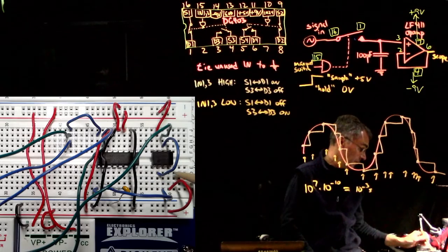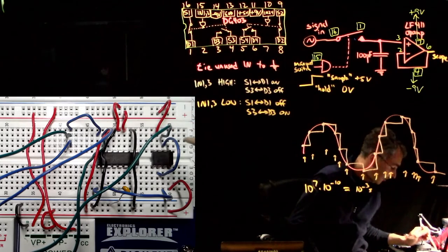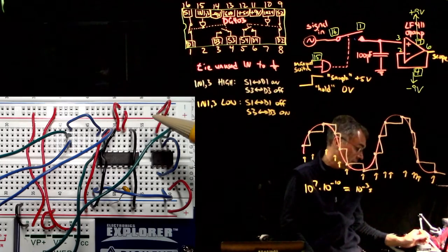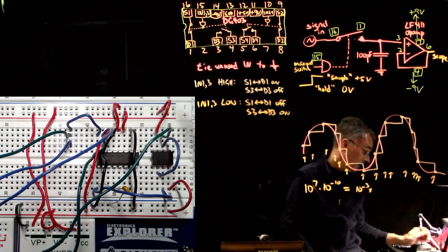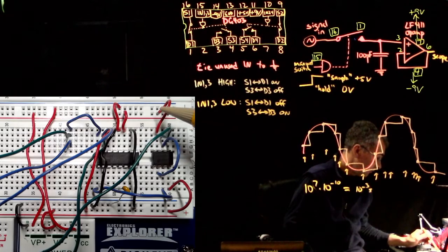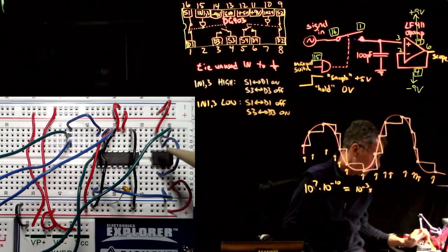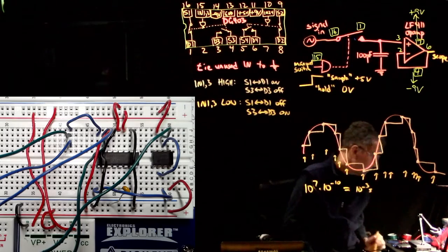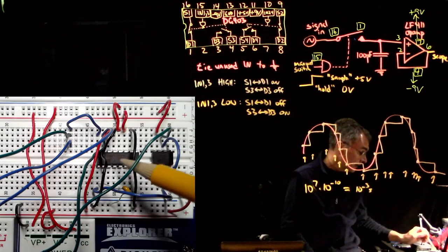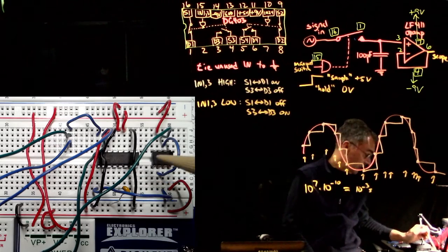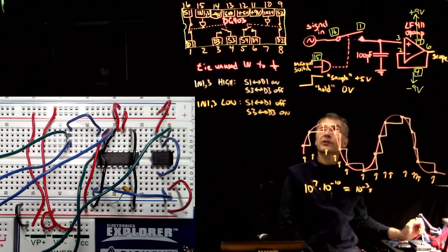And then pin 4 is our negative power, that's minus 9 volts. Pin 5 we're not using. Pin 6 we talked about. Oh no, this is also pin 6. We're watching pin 6 with scope channel 2, which is going to be the blue or cyan colored channel. Pin 7 is plus 9 volts power, and pin 8 we're not using. Okay, then the connections in the DG403 are pretty much the same as the previous video.